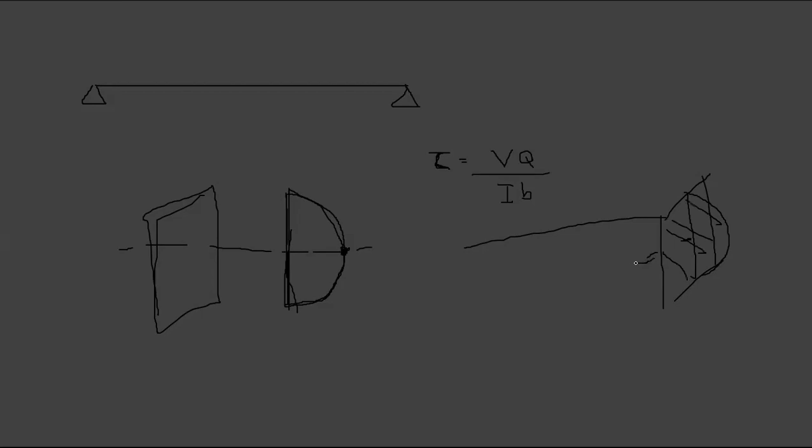So at the neutral axis, the beam can fail in shear, where your shear stress first reaches 3 megapascal, because this is the highest stress. That means it reaches the failure stress first. Let's say this is 10 and this part is 2, so let's say it fails at 20.